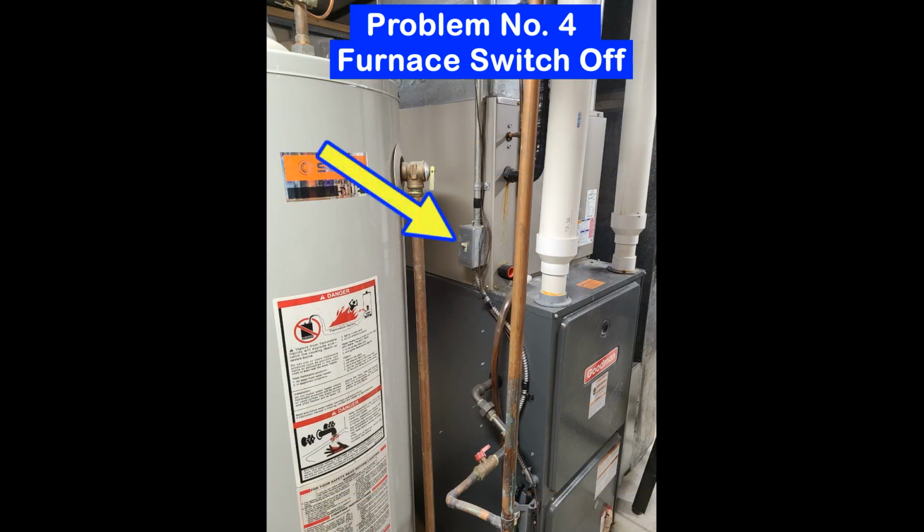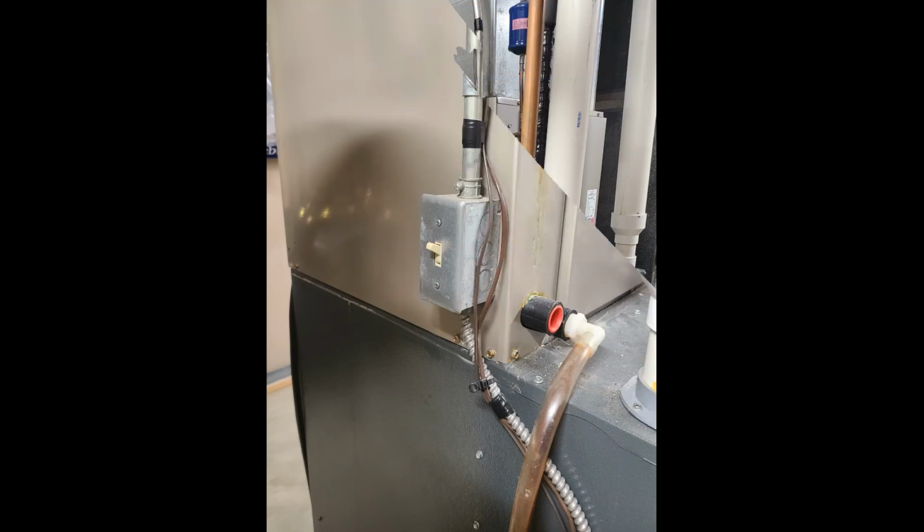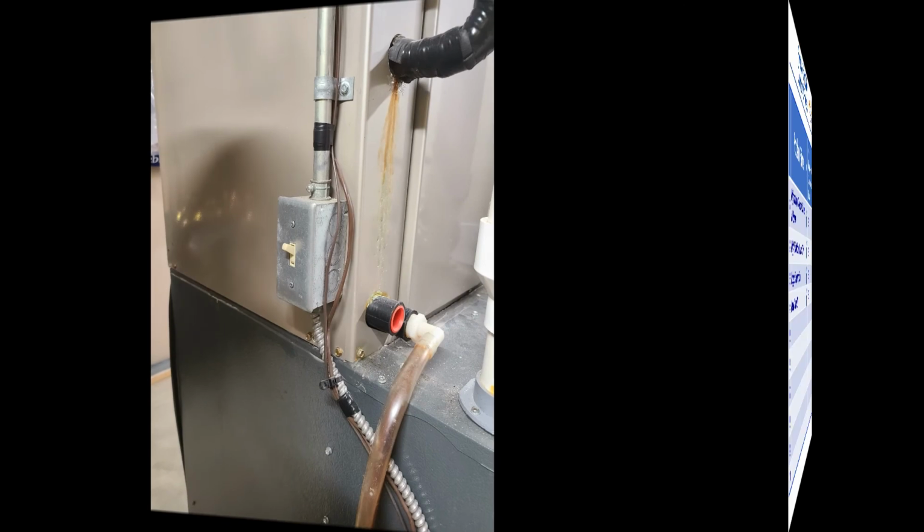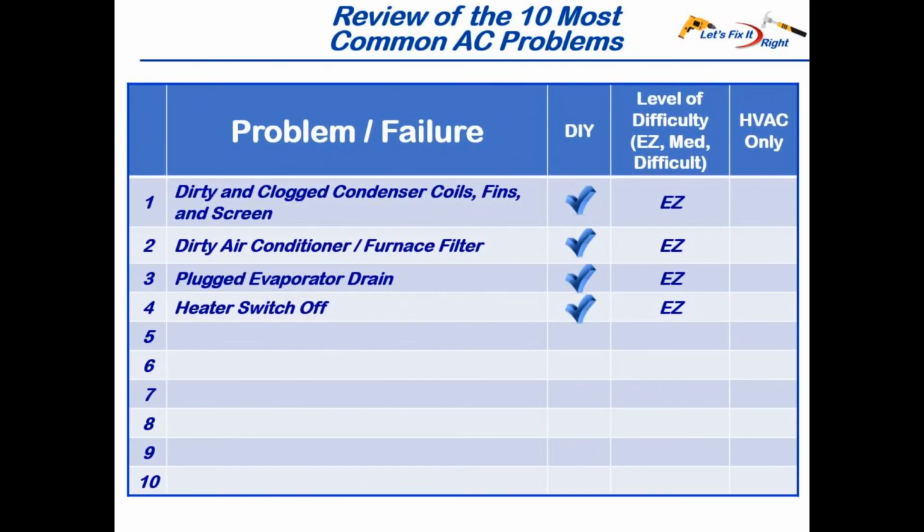Most municipality building codes require a furnace switch close to the unit, so it can quickly be turned off for safety purposes. While changing your furnace filter or cleaning around your furnace, it's possible that you could inadvertently turn the switch off, or one of your kids may turn it off while playing in the basement. If this happens, neither your furnace or your air conditioner unit will work. If your air conditioning system will not come on, check this switch to ensure that it is on. This is also an easy do-it-yourself task.